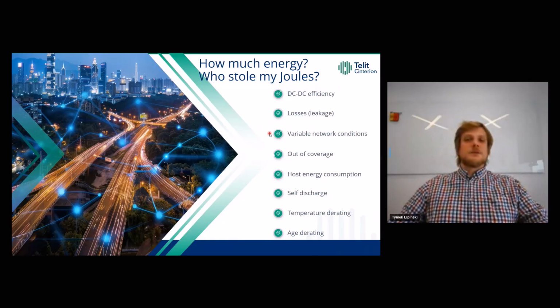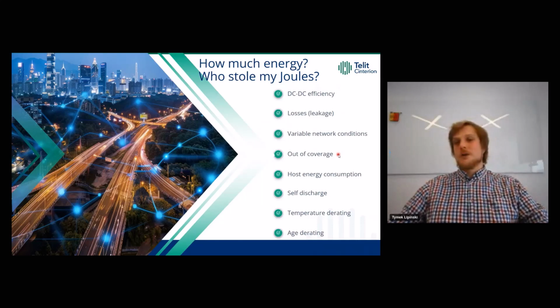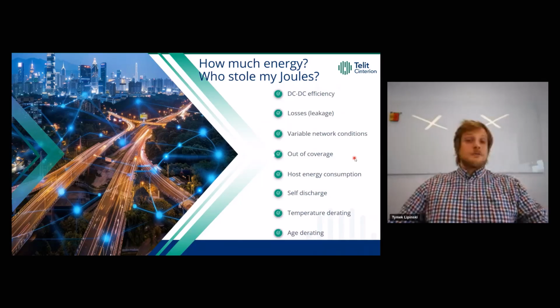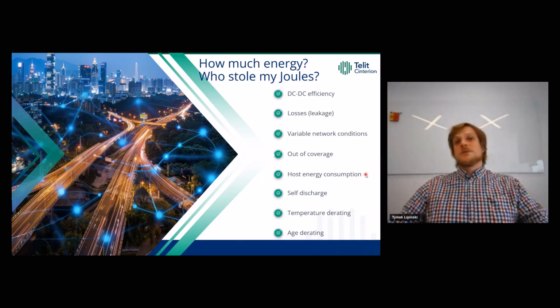We have variable network conditions. The network coverage may be pretty bad, or somebody took our device into a basement and the modem is struggling to communicate with the network. We are out of coverage, so the modem keeps scanning the network and consuming power to decode every single available channel because it's struggling and wants to attach to a network. We have to factor in our host energy consumption. Have we achieved maximum current saving and power saving on our host device?